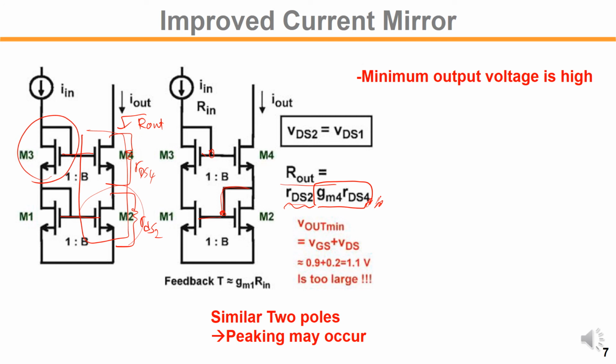But for the cascode output, although the cascode can improve the output impedance, we are actually wasting a large voltage headroom for signal. If you look at this structure here, you require that the source nodes, left and right, be similar or the same, because we are sharing the gate voltage. For example, with B equal to 1, we have the same VGS for those two devices, meaning those source nodes must be matched.